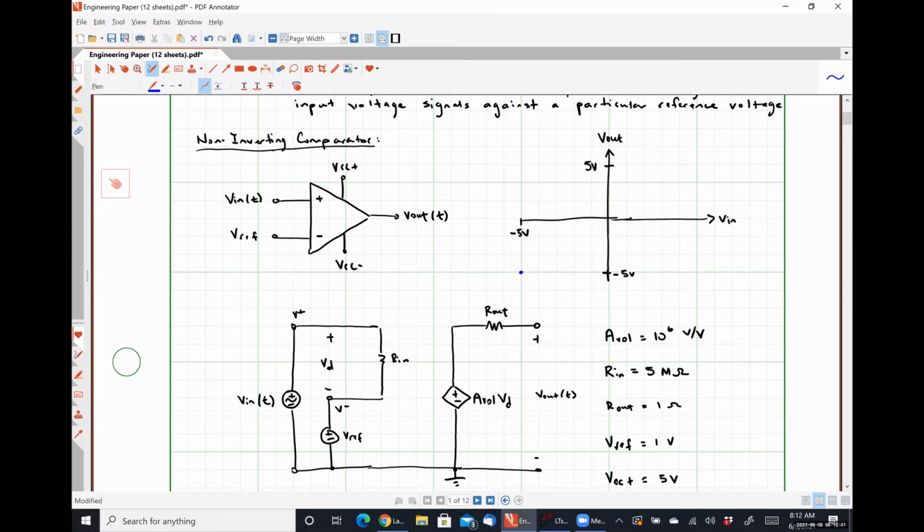So at Vn equal to 0 volts, we also have an output voltage of negative 5 volts. We okay with that? Does anybody have any problem if I connect these two dots with a line? So I'm suggesting here that if my input voltage is within the range from negative 5 volts to 0 volts, my output is always going to be in negative saturation. I shouldn't expect any abrupt shift, right?